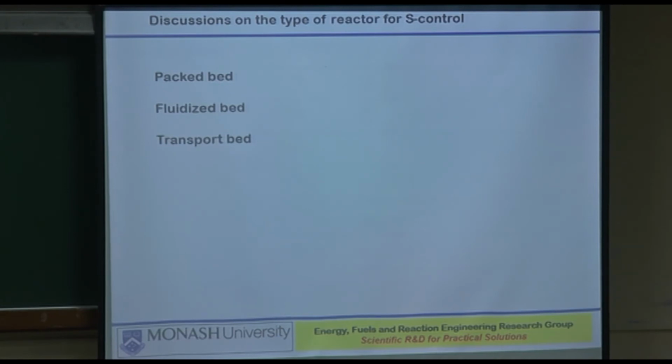Once the plant is designed, you are not increasing the fluidization velocity. Fluidization is always fixed, yes. How else can it increase? Unless you are generating more gas, it cannot. Or unless you are putting in more nitrogen. You will put in more nitrogen only at times, but otherwise it's all fixed. So if pressure drop changes over a period of time, that's telling you some problems are happening. You'll have to look after the bed.